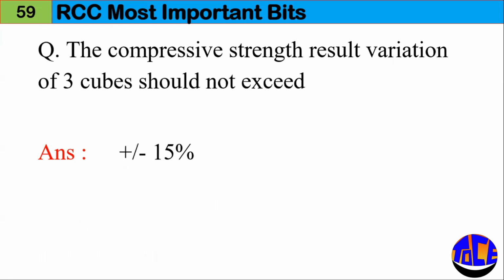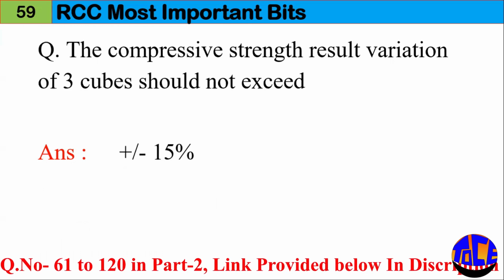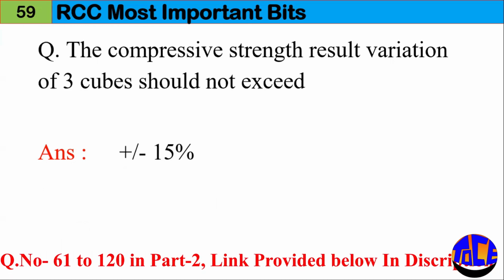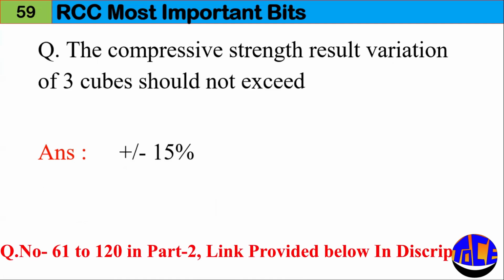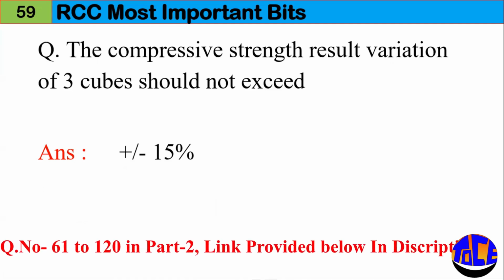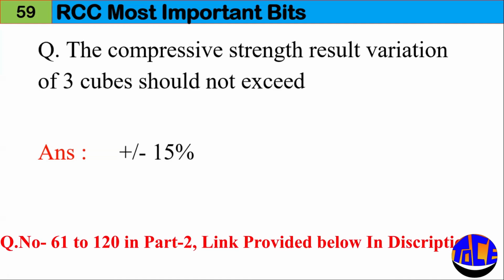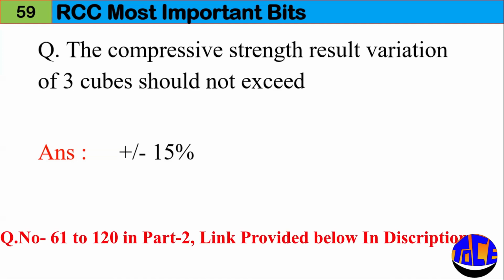Let us see question number 59. The compressive strength result variation of 3 cubes should not exceed plus or minus 15%. So the 3 cubes strength should not vary by plus or minus 15%. If it exceeds this, you should not consider that cube strength.